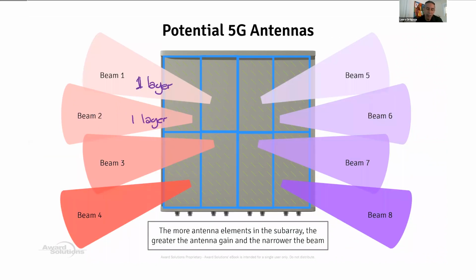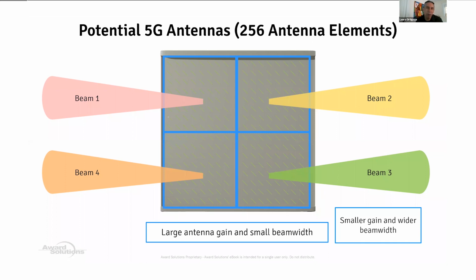So you saw the size of the radome. Look at the size of the antennas when you drive. They're huge, right? The radomes. I cannot put many antenna elements there. Therefore your beams are going to be really wide, because I only have four antenna elements. So my beams are 120 degrees or 60 or 70.